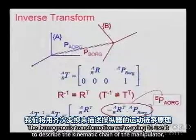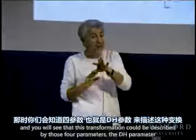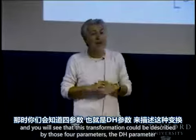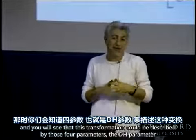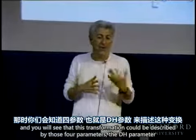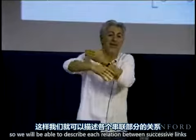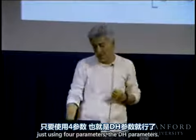The homogeneous transformation, we're going to use it to describe the kinematic chain of the manipulator, and we will see that this transformation could be described by those 4 parameters, the DH parameters. So we will be able to describe each relation between successive links just using 4 parameters, the DH parameters.